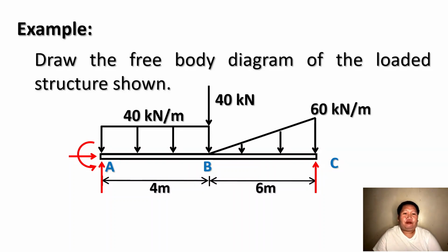So now this is the free body diagram: the body with the translated reactions. In this type of illustration, the next thing to do is get the equations done: the summation of forces, vertical and horizontal, and moment. Those are the three equations that we will be revolving our solutions around. So let us proceed to our example.